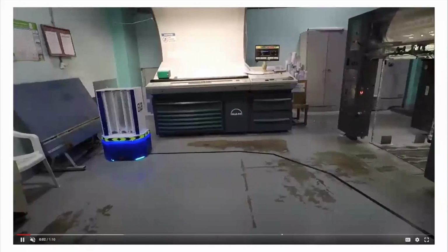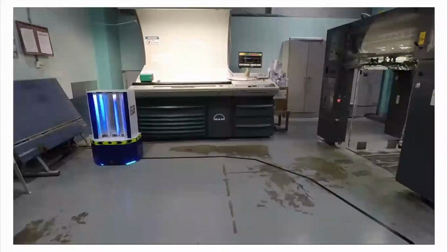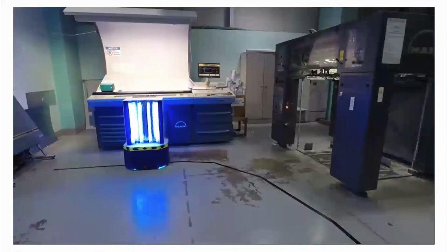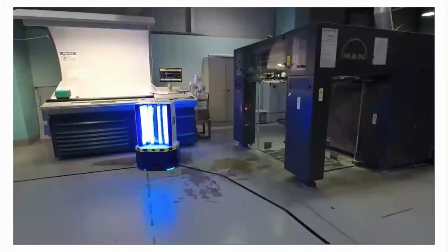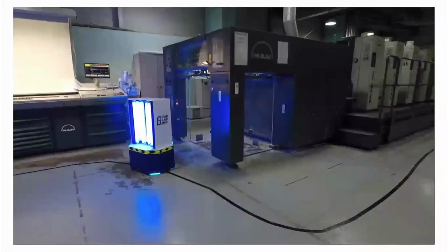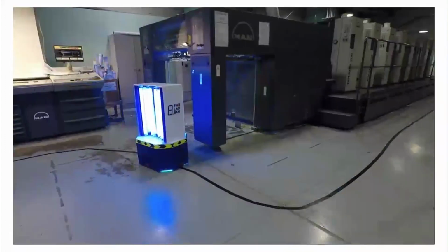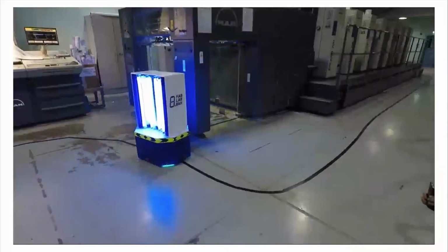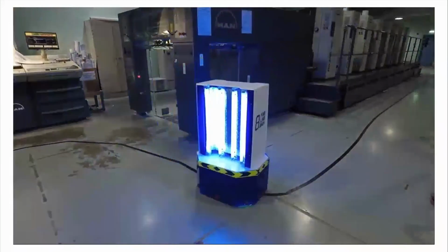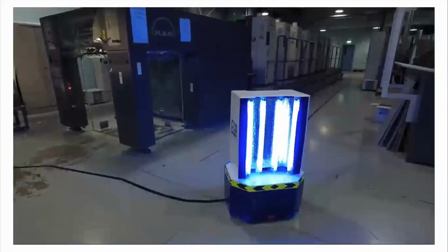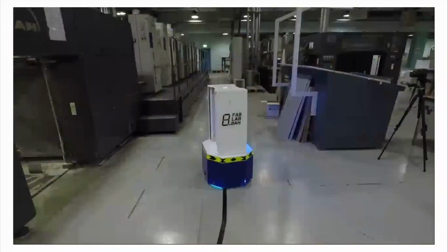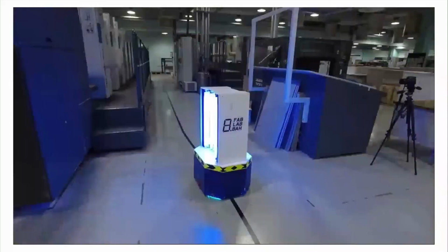Okay. Here is our UV light robot. We have two modes of operation. This is the first mode of operation, which is a line follower. The basic function of a line follower is that we will draw a line going around the machines in the working area, so that it will take a specific path for sanitizing the place. And once it reaches the end, it will stop by itself with a special algorithm made for it. When it sees an ending line, it just stops.